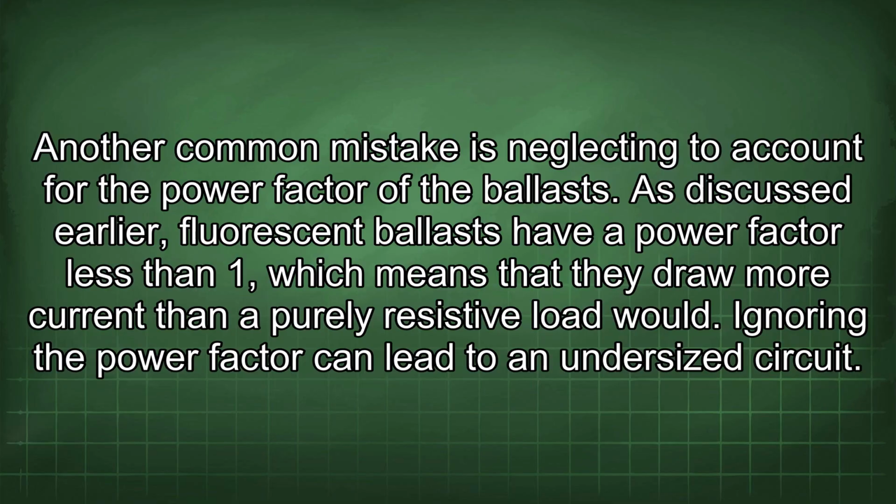Another common mistake is neglecting to account for the power factor of the ballasts. As discussed earlier, fluorescent ballasts have a power factor less than 1, which means that they draw more current than a purely resistive load would. Ignoring the power factor can lead to an undersized circuit.